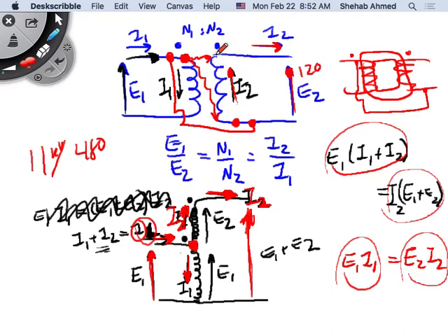But with 11 kilovolts, I highly doubt it, right? So the transformer isolation is a big safety issue. We lost isolation, but we still got this benefit of stepping up, stepping down, and we're able to push more power through. So what is the use of this transformer? If I cannot use it safely on the distribution system, the best use of this is on the transmission side.